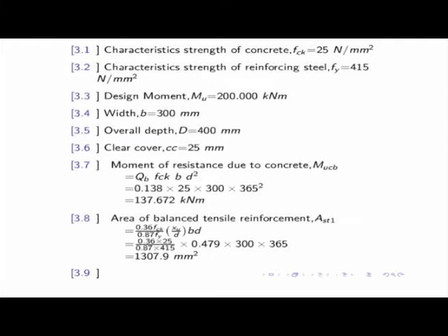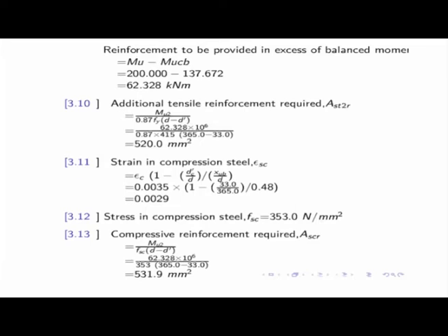So you will not be able to achieve the full strength of the steel, which will be less than 0.87 fy. In that case, you will find out the value of that stress, and you can find out the corresponding area of steel. Obviously, if you compare both of them, say 531.9, which is coming a little more than the value that you are getting, then only you can say it is now in equilibrium position. So this is the idea of the doubly reinforced section.